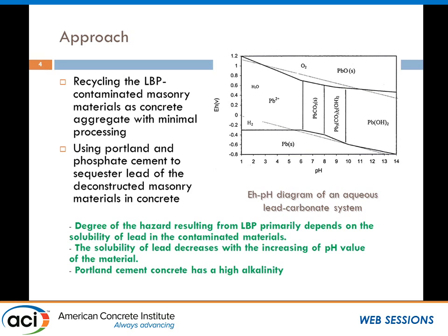Because based on the classification, it is not just the total lead in a material that counts. More importantly, it's the leachable lead, how much lead can get out from a material. That's what counts. So that's the main idea, to use the high pH of concrete to keep the lead inside a new concrete.